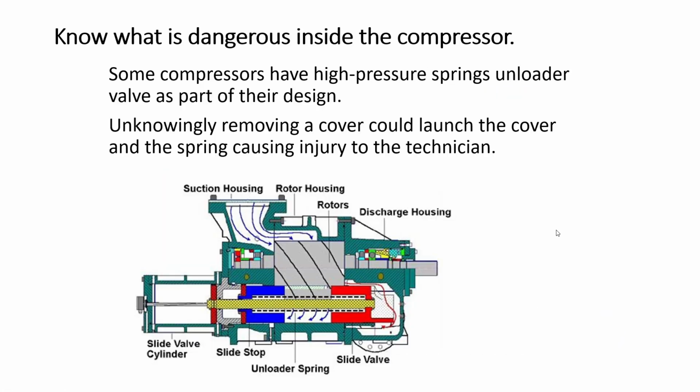Now let us see that there is something very dangerous inside the compressors, which has spring loaded flow control valves. So these are high pressure valves, and if, carelessly or unknowingly, the cover is removed, there is a chance that it may come and hit the technician. You see the springs are here.